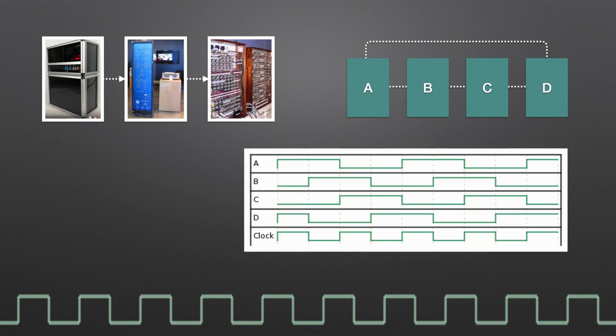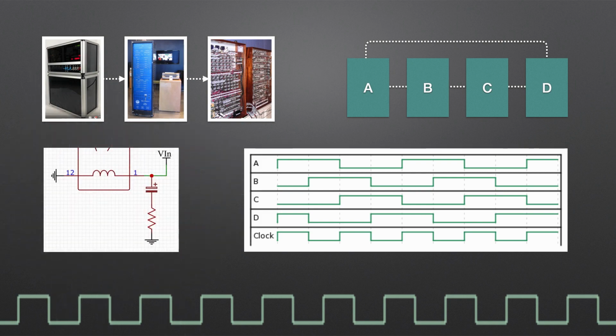The magic behind the magic here is the use of an RC network at each relay coil to control the length of time each relay is held on after its power supply has been cut. Pros and cons wise, this design is very authentic in my view, but operates at a fixed clock speed. Once designed and set, that's it. It'll also be a challenge to get the resistors and capacitors set at an appropriate value to get the exact clock timing I'm after. It might be slightly off 6 Hz, but not so much it'd be a problem.